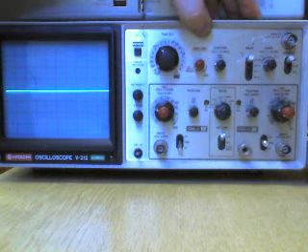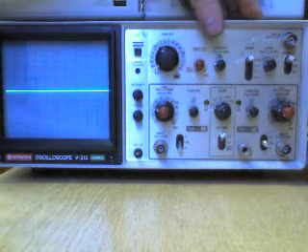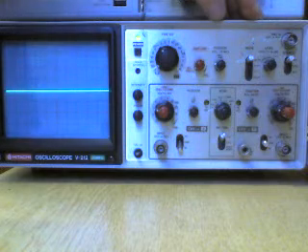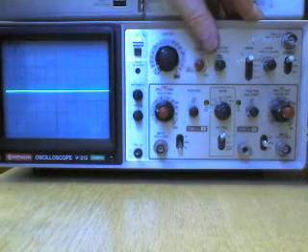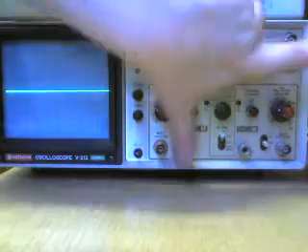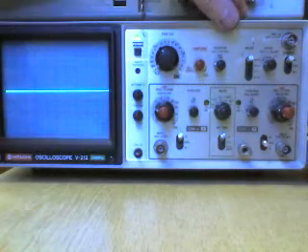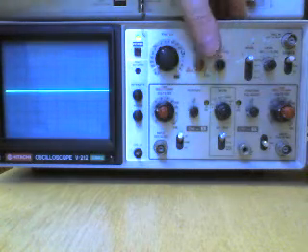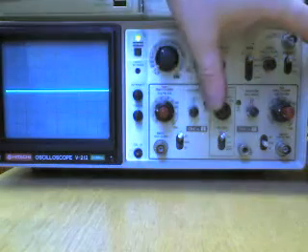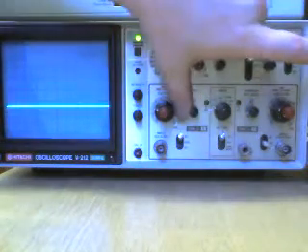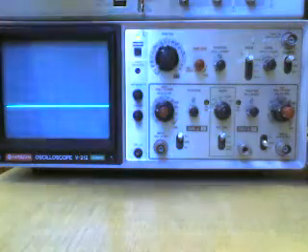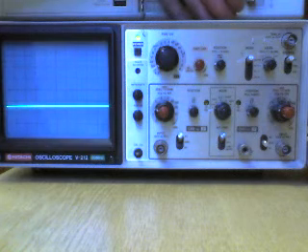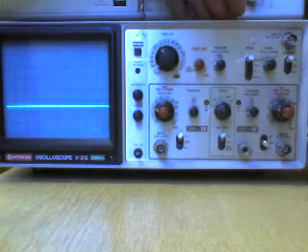If it's a sine wave with a DC offset, your sine wave no longer oscillates around 0, it actually oscillates, say, around 1 volt, or minus 1 volt, for example. Then you would have to switch it to DC because it's got that offset on there. If you had that switched to AC, the scope tries to remove the DC component and tries to recenter the waveform around 0. So if you had a nice flat DC signal input on here and it was on AC, all that you would see is 0 volts. If it's AC and you had a DC component in it, all that you would see is the AC, and your sine wave will be oscillating around 0. You wouldn't get to see that DC.